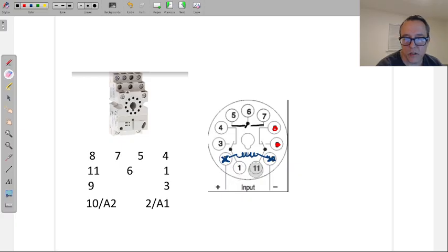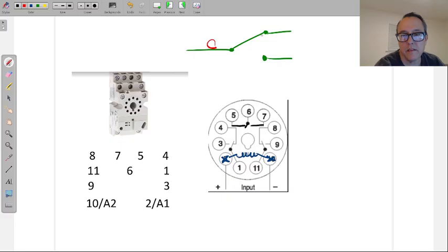That's a good question because it brings up something else, which is identify the common. Oh, 369. Right, when you have a 3-pole double throw switch, technically you have a common, a normally closed, and a normally open. So one of the first things you want to identify, and this is just the way I like to read these, is the common. In this case, the 6 is the common, in this case the 11 is the common, and in this case the 1 is the common.